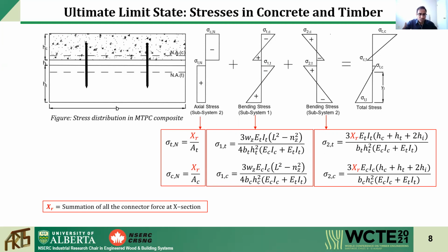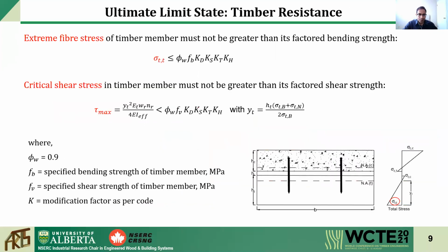After adding up all the stresses, our main focus will be to get the stresses in this zone. So we need to figure out the stresses at the top and bottom of the concrete, as well as the bottom of the timber. Then we need to check the resistance of timber as well as concrete.